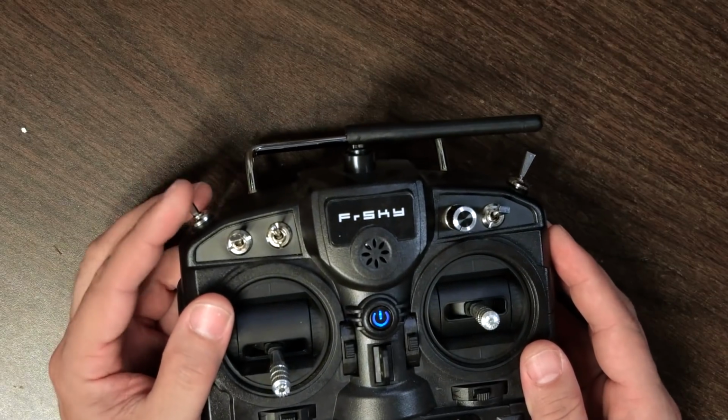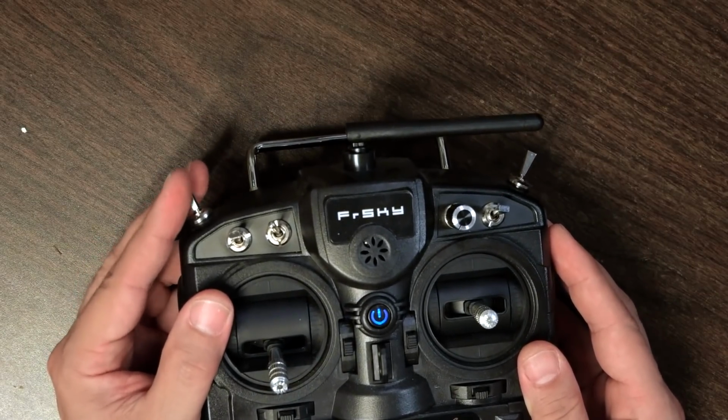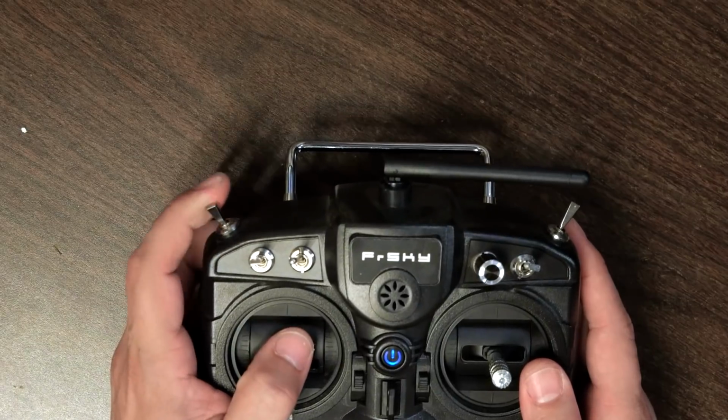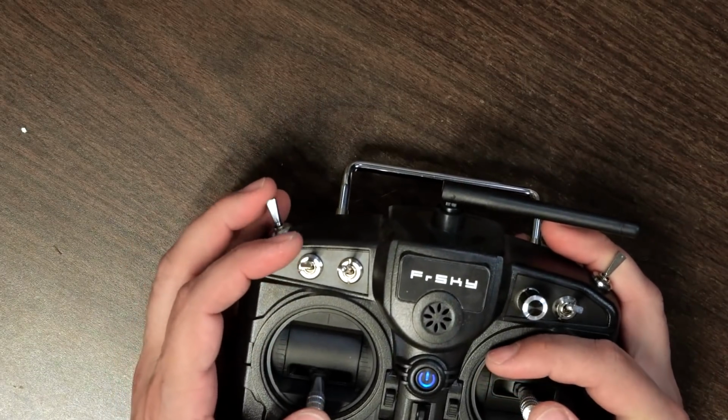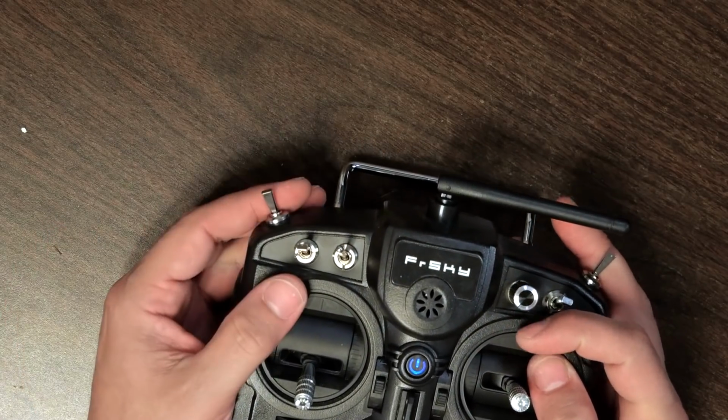One of the things that's both frustrating and liberating about this type of controller is that the switches are not predefined in any way. You can set the switches up to do anything you want, but also they're not set up from the factory to do anything at all. So I like to use this 2-position switch on the left shoulder to arm and disarm the quadcopter. It's really easy to get at when you're flying, so it's a 2-position switch, arm, disarm. So let's just decide that that's what we're going to do.